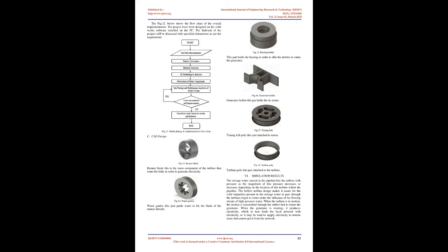OJMO et al. designed a Picohydro prototype to harness the energy contained in falling water. The turbine used had a runner with a single jet and bucket geometry, was hemispherical, having 50 mm diameter. The hydraulic head was 3.4 meters and the reservoir capacity was 2,000 gallons. Results showed that this prototype was able to produce 4.5 W of electricity with turbine revolutions of 500 rev/min. They reported that the power generation could be enhanced if the system can be upgraded to a scale of 110 for the diameter of a runner, head, and capacity of the reservoir with a step-up transformer.